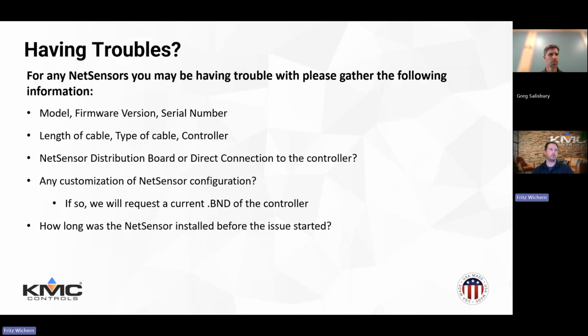If you do happen to run into troubles with the NetSensors, I wanted to breeze over some of the questions that you're going to get if you call in to tech support, right? They're going to be looking for a lot of information from you to help us narrow down and troubleshoot what that issue could be and how we can help you there. So I'm not going to read through all these bullet points, but it's good to know model, firmware revision, serial number, the length of the cable, type of cable. Was there any special customization of the NetSensor? And if that's the case, a backup of the BND file for us to reference and take a look at.